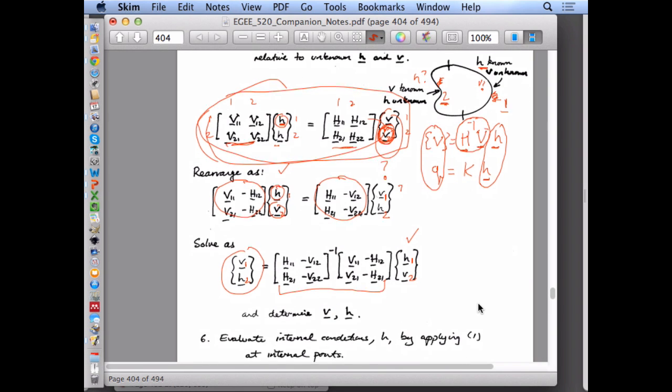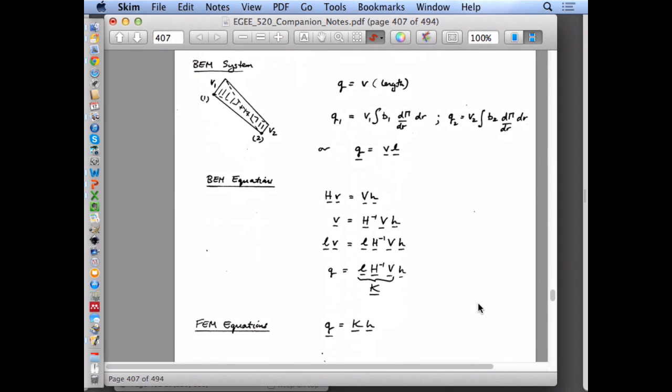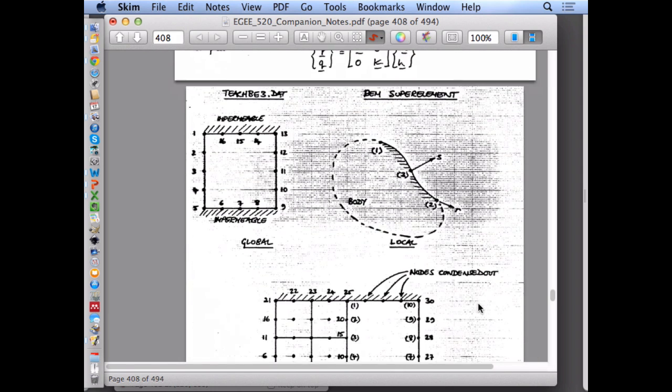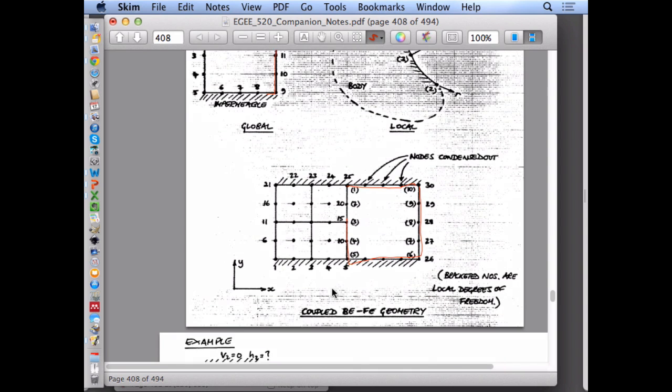And so if you want to, you can actually interface these by using the same kind of, and this is the discussion of how to couple them together, just by trying to make super elements. So this could be our geometry that we just solved for in our very simple example, but instead of using 4 elements, we're using 1, 2, 3, 4, 16 elements with nodes at each end, and then attempting to interface this big conductance matrix with a whole bunch of smaller finite element matrices.